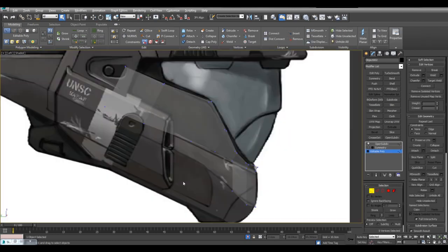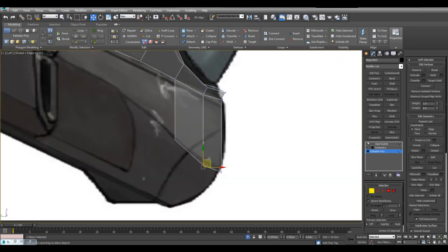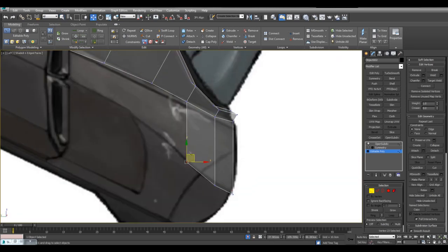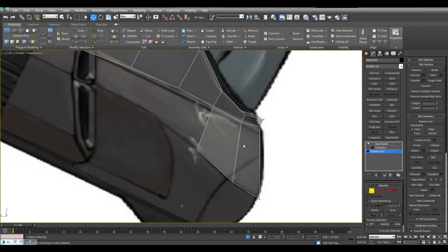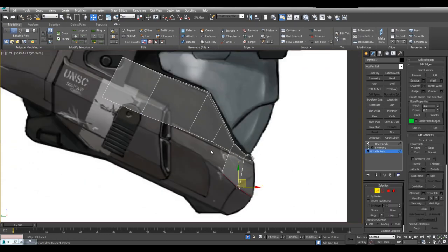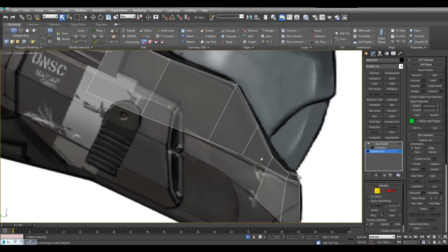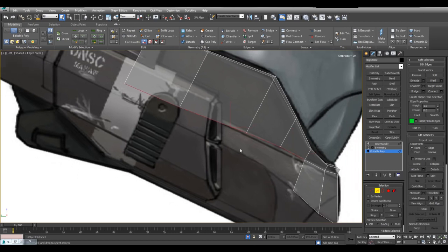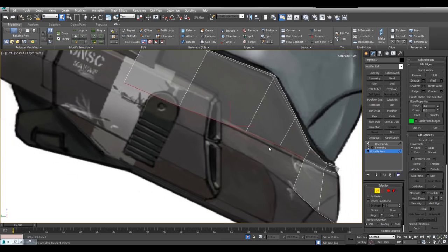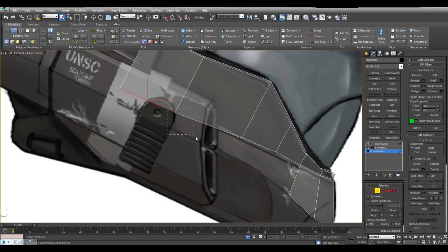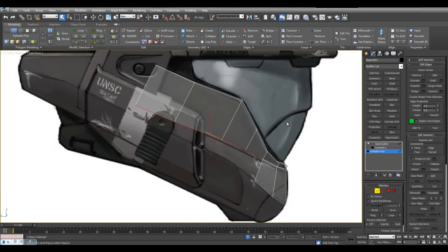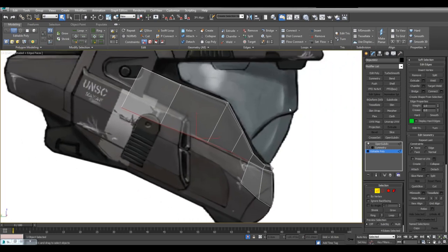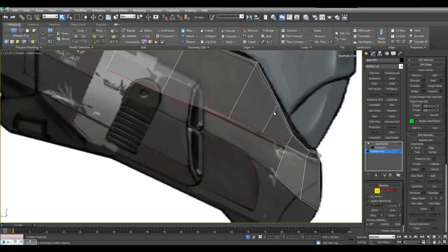And then go to the left viewport and just kind of adjust a little bit more. Shift V, edge constraints, and just kind of clean things up a little bit. Here I will press Shift S, step mode, select, hold Control, select to select these 4 edges here. In this case, I can really just select it like this and then hold Alt and deselect. But it's a good idea to get used to using step mode. It will definitely come in handy when you have much more complex objects.